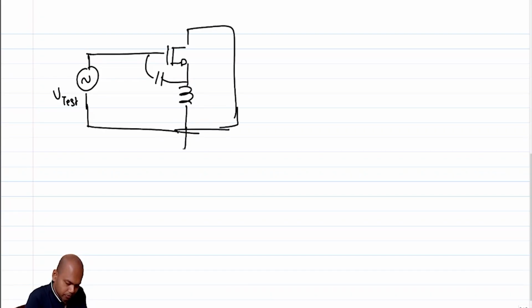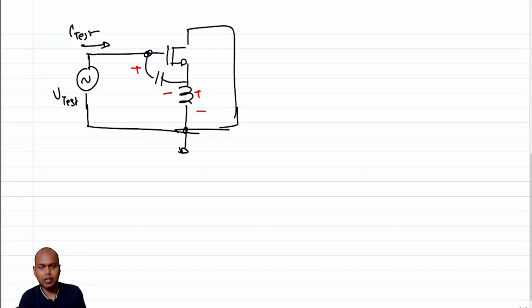So whatever I test we get, V test over I test was our Zin. And we understand that the resonance is happening because of this L and C in series. If I want to shift the resonant frequency without affecting that term omega t times Ls, what can we do? The simplest thing that we can do is probably put an inductance here, and let's call this Lg.